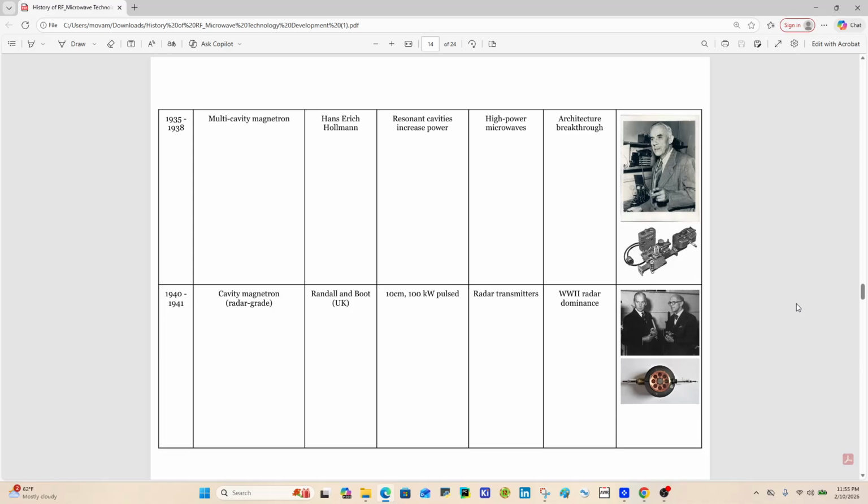And in 1940 we had the cavity magnetron, which is the penultimate magnetron used for radars and the microwave ovens that we know and use today. The cavity magnetron was capable of producing hundreds of watts in a centimeter wavelength, and it had a very high efficiency, and it was the first practical high power microwave source. It had a strong nonlinear interaction. The relationship between the electron velocity and the RF phase velocity determined how much energy you can pull out of the magnetron, and this was used in airborne radar, submarine detection, and aircraft interception. And it really became a military and industrial workhorse.